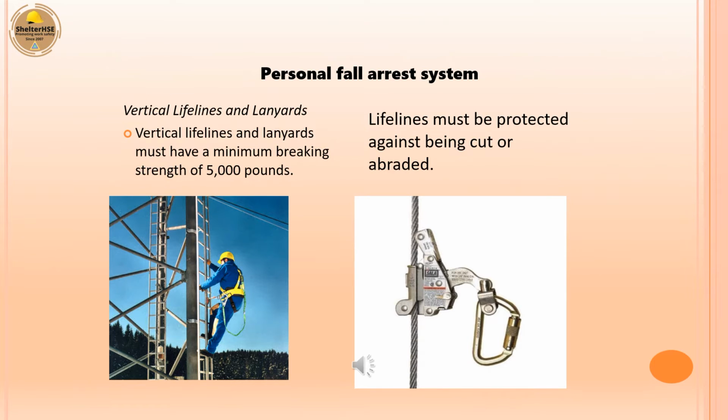Vertical lifelines and lanyards. Vertical lifelines and lanyards must have a minimum breaking strength of 5,000 pounds. Lifelines must be protected against being cut or abraded.